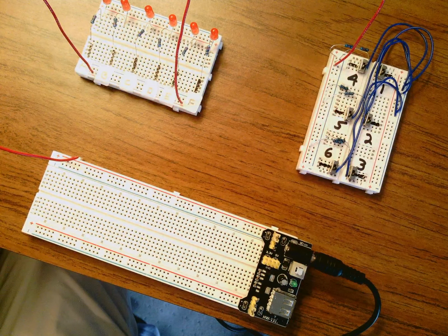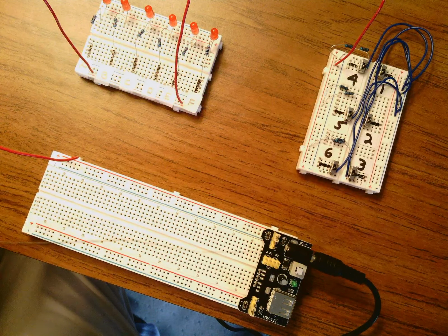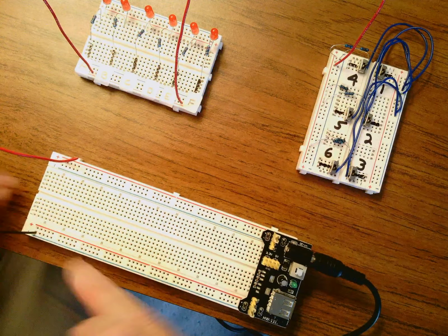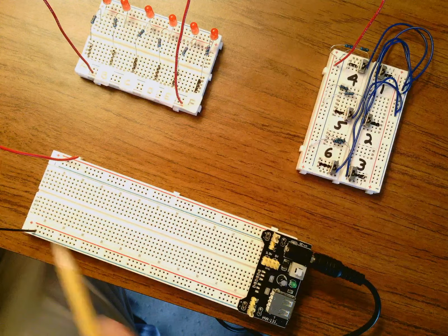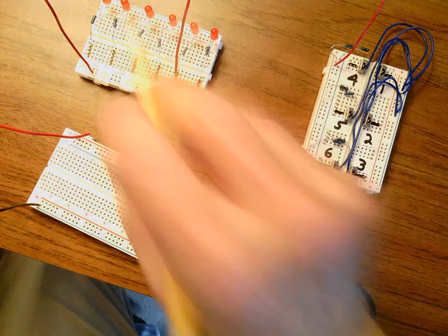I have black wire. I provided you with 4 pieces of 15-inch black wire, but you're only going to use 2 of them now. What I'm going to do is go from the ground rail here. This power supply puts 0 volts, or ground, on this bottom row the whole way across here. I'm going to distribute that the whole way up to the blue rail on this upper board. You have to be careful. I don't know if you can see that, but I have that plugged in at the very top on the blue rail there. And now I have to continue that and distribute it here.